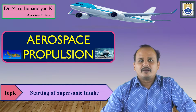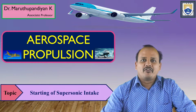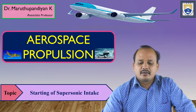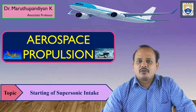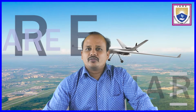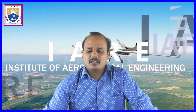So in the previous lecture we were discussing the supersonic intake, how they differ from the subsonic intake, and what design complexities we face when we start designing a supersonic intake. Then we saw the different types of supersonic intakes, that is internal compression, external compression, and mixed compression intake. So we have classified these intakes based on where exactly the shocks are present.